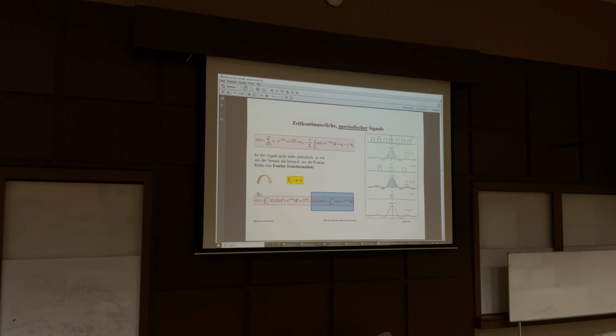This sum is represented now by the Fourier transform. And the Fourier transform, again like in Laplace, is indicated with capital letters. If we have an x of t, the CKs are our components in case of a periodic signal, and that converges into a capital X, the Fourier transformation.